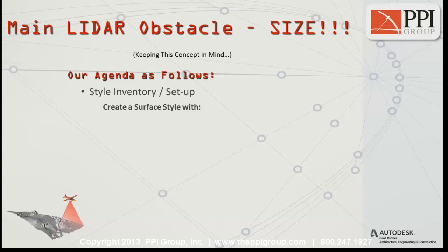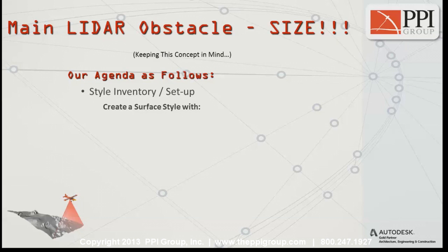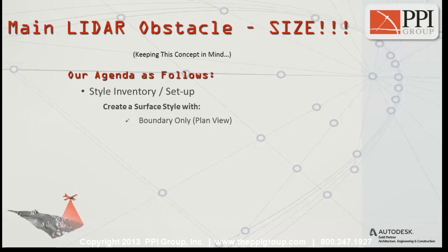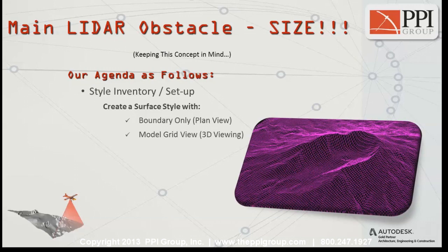So let's drill down just a bit here, talking about the styles. Again, I'm not going to go too deep into this, but if nothing else, I want to at least create one with you, as it'd be a good tool for you moving forward. Basically, we're going to start with the boundary only style, which, if I'm not mistaken, does come with the product, so odds are you already have this one. We'll copy that, and then we'll go into it and enhance it, I should say, and add what's called a grid view for 3D viewing.